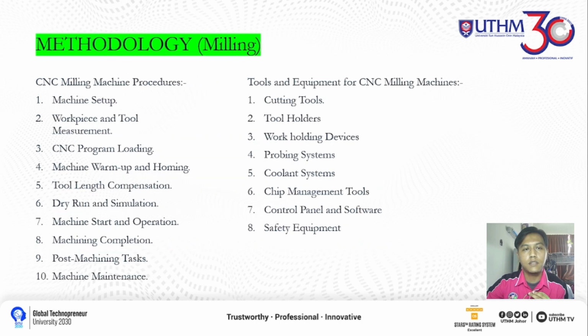Next, the CNC milling machine procedure. Machine setup, workpiece and tool measurement, CNC program loading. Next, machine warming up and homing. Next, tool length compensation, dry run and simulation, machine setup, machine start and operation, machining completion, post-machining tasks, machine maintenance.